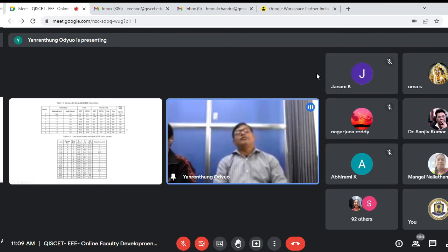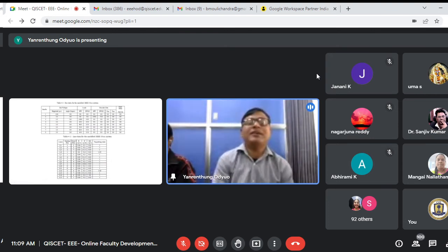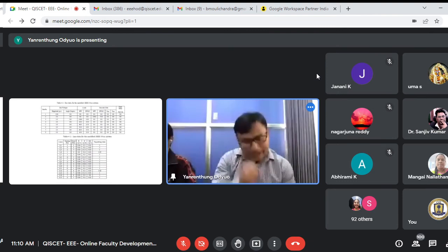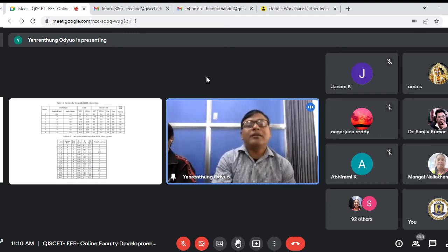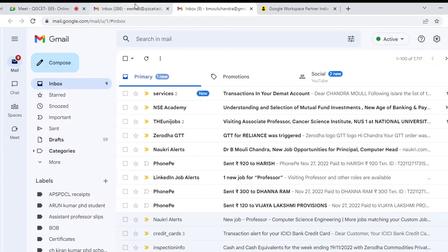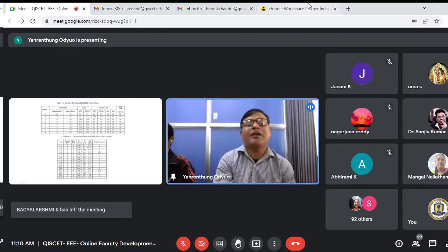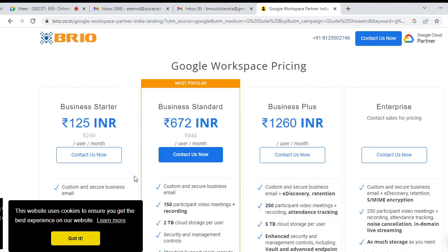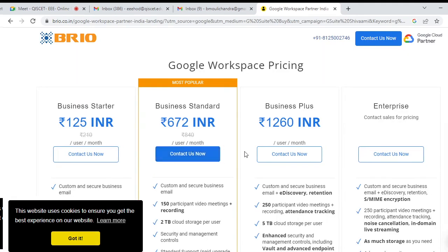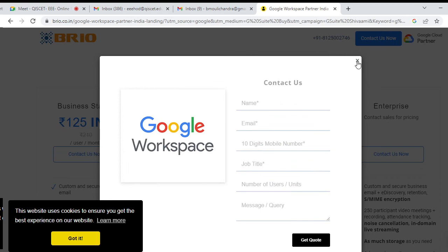Table 1 refers to the bus data of the system, and table 4.1 and table 4.2 reflect the line data, or feeder data. So for the feeder, the starting bus and end bus are given, and in between, the r value, x value, as well as the b value are given. In some cases you see the tap setting is normally 1, but wherever a transformer is there, some tap setting value is there.